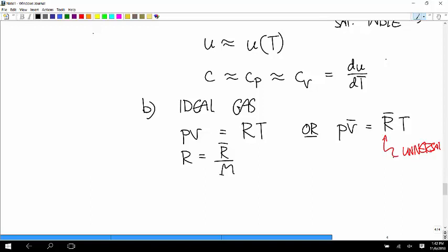Yeah, that's the same as that because this is volume per mole. So multiply the moles over here, and you get P times real volume is equal to number of moles times RT. But yeah, that's sort of the chemistry version. And really, the only reason that we use the other version is because the tables we use have all of our specific properties. They could just as easily write out those tables in a molar form, and then we would use the one that you're more used to.